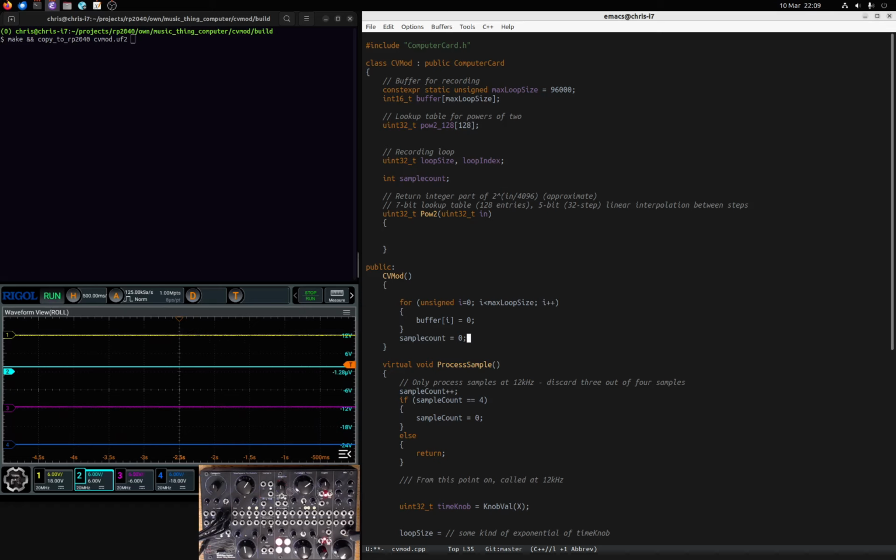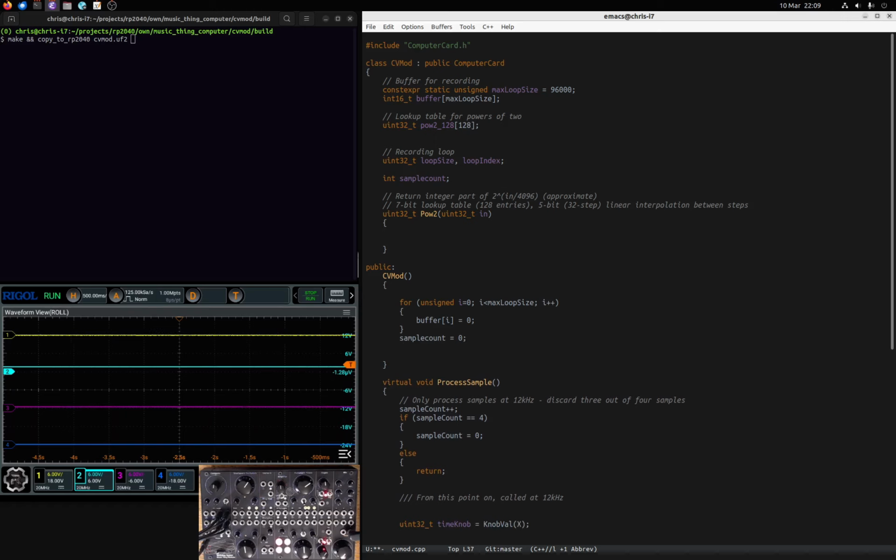One of the nice things about the RP2040 is that even though the floating point stuff is a little bit slow compared to the integer, you do have it available, and that means that rather than generating lookup tables using some pre-calculated numbers from Python or something which I just paste in the code, we can generate it live in the constructor. So what do we need to do?